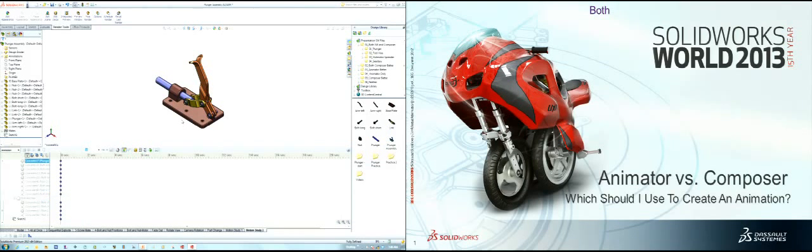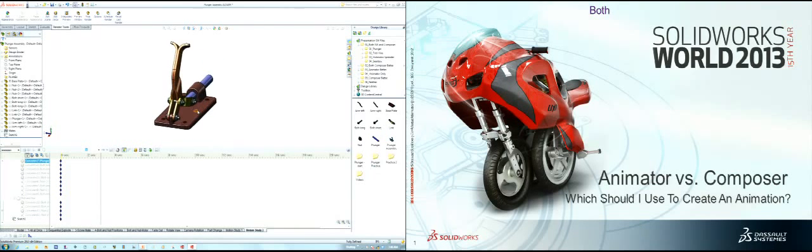So now everything is just sitting wherever it used to be. When you make an animation, we can move the timeline ahead, and all the key points tell us is, at this key point, you be at this location. At this key point, you be at some other location. And then we allow the software to get it from A to B. So if I move my timeline ahead to 3 seconds, I can now take these 3 nuts and move them.